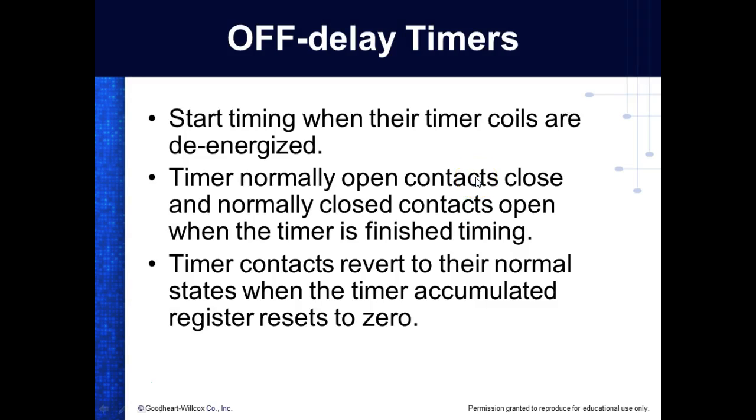Off delay timer: starts timing when the rung becomes what? False. Everybody understand that? So timers are output instructions. We need to make sure the timers go on the L2 side, right? Everybody understand that? Can you put more than one timer in a rung?